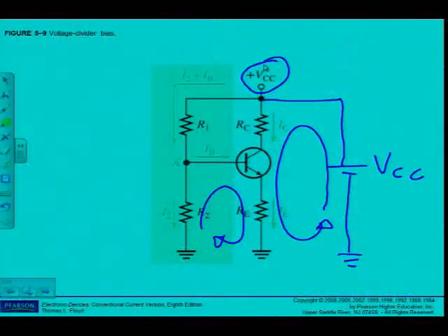Okay, so if I go and look at the voltage divider circuit as we have here, remember, I have to determine VB. Where is VB? Let me just go back to my circuit there. VB is the voltage at the base. Remember, previously we had a separate supply here and not a voltage divider.